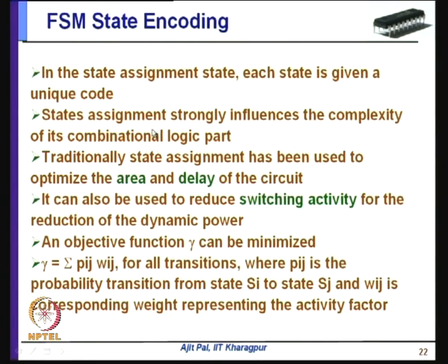Apart from clock gating the finite state machine, you can do finite state encoding. As you know, whenever you realize a finite state machine which has got different states, each of these states is to be encoded. State encoding is usually done to reduce the area of the circuit.